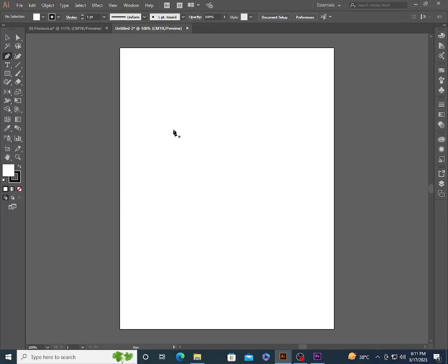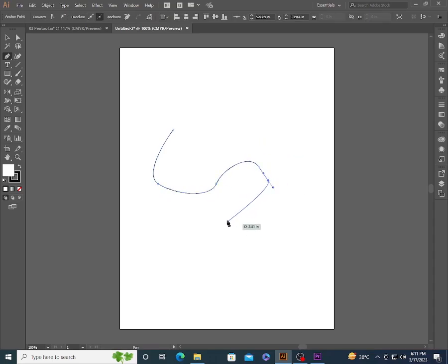Here we have a pen tool. Just click and start working. Click the start point, and then the next point. Hold the click and drag it for a smooth line. This line will continuously follow your mouse until you press the Escape key or click while holding the Control key on an empty place. If you click by mistake and want to continue, pick the pen tool again.